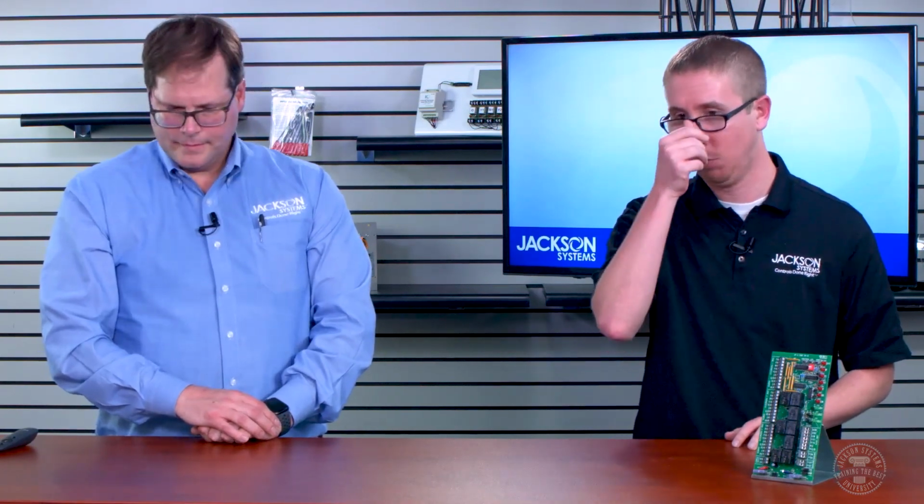Yeah. So Zone 1, this is a particular product. Zone 1 is the name of the product, right? Zone 1 is the name of a product. There's 2 options. There's a modulating one and a 2-position one. The modulating one is quite a bit more popular, to be honest. What it is, it's a thermostat, and it's wired to a zone damper. That zone damper is going to have a tiny printed circuit board on it.